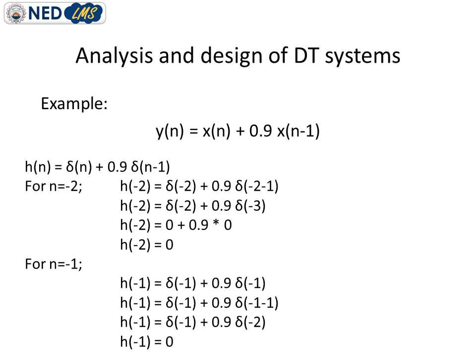First of all, we put, arbitrarily, n is equal to -2. We can also start from n is equal to -3 or -4. But as we can see from the equation, the input is delayed by only one unit, so it is feasible to start with -2. If the equation were delayed more, then we could start with -5 or -6.